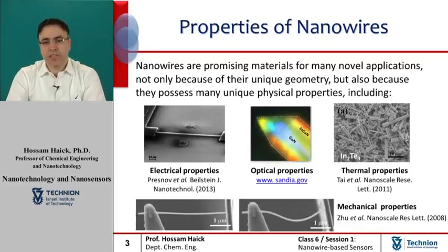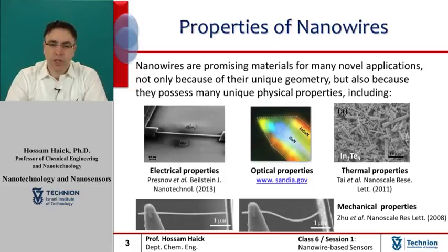As a representative example of this property, you might take a look at the hierarchical nanowire structure that is made from indium telluride, as presented in the right side figure of the top panel on the screen. This nanowire exhibits a remarkable enhancement in the Seebeck coefficient of about 43% over that reported for the corresponding thin film at room temperature.